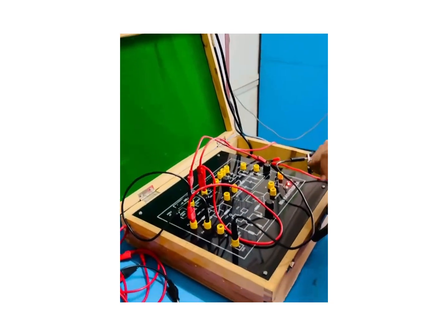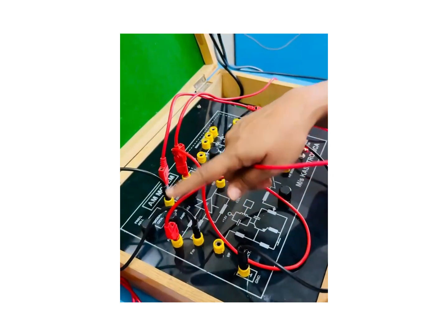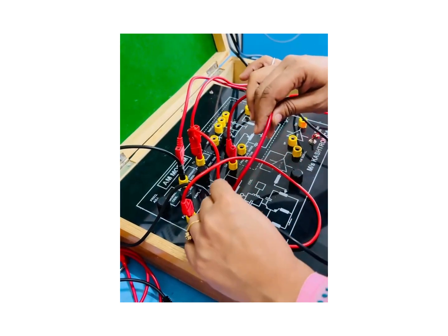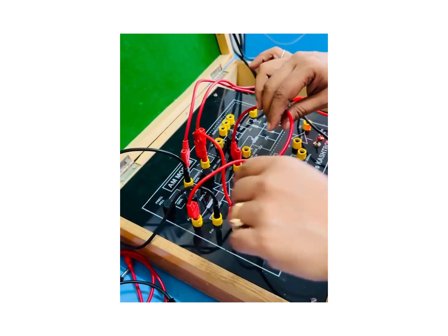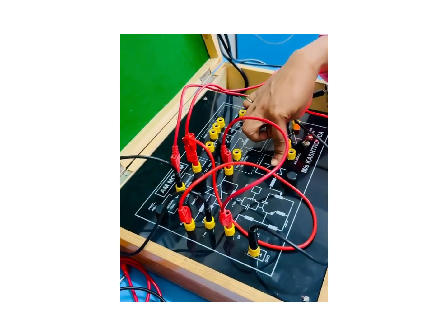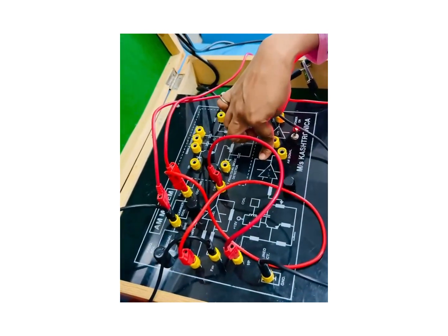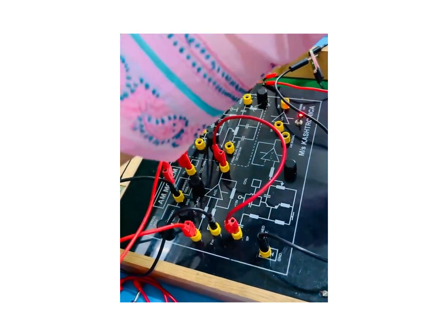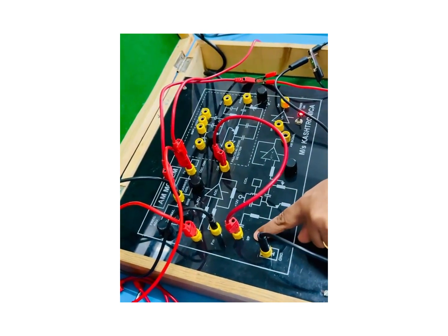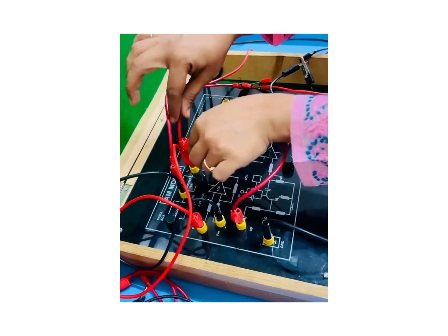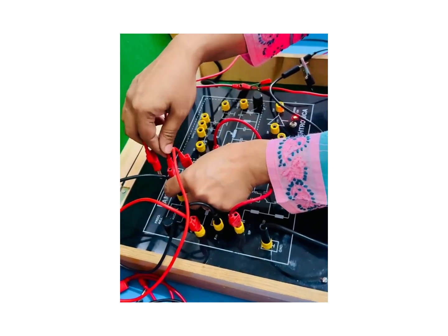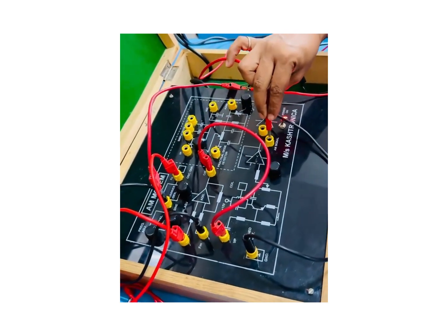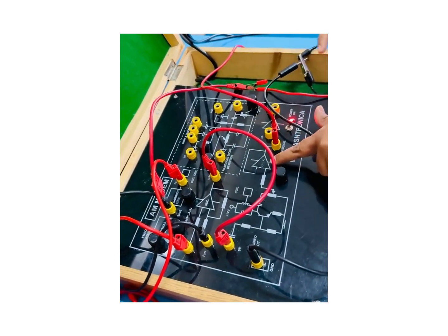So with this adjustment of modulating signal frequency and amplitude of carrier signal, let's move on to the observation of the modulated signal. Now we have connected FM and FC to the inputs of adder. Now the output of adder will be applied to the input of tuned circuit. Now the output of tuned circuit is a high frequency carrier, but its amplitude will be changed according to the input, that is addition of amplitude of modulating signal and carrier signal. We'll observe this modulated output with reference to modulating signal. The output or AM signal is observed at the output of the buffer.